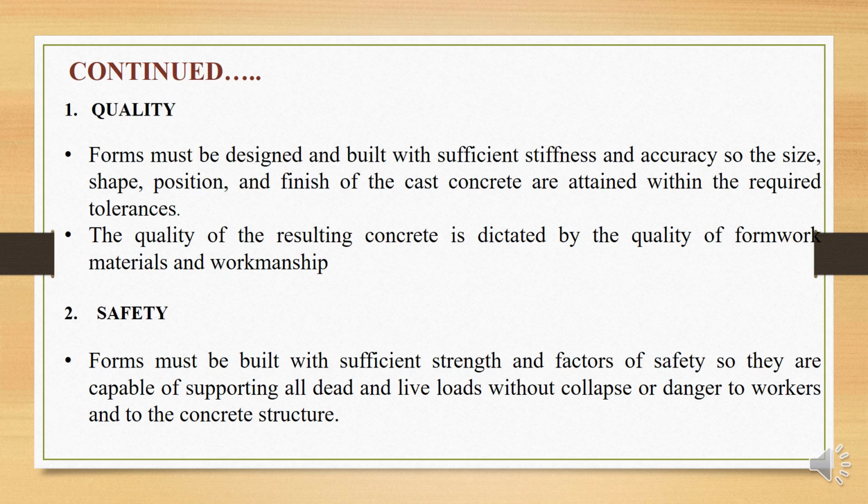Next is safety. Forms must be designed with sufficient strength and factor of safety so they are capable of supporting all dead and live loads without collapse or danger to workers and to the concrete structures. Formwork operations are risky and workers are typically exposed to unsafe working conditions. Partial or total failure of concrete formwork is a major contributor to death, injuries, and property damages within the construction industry.